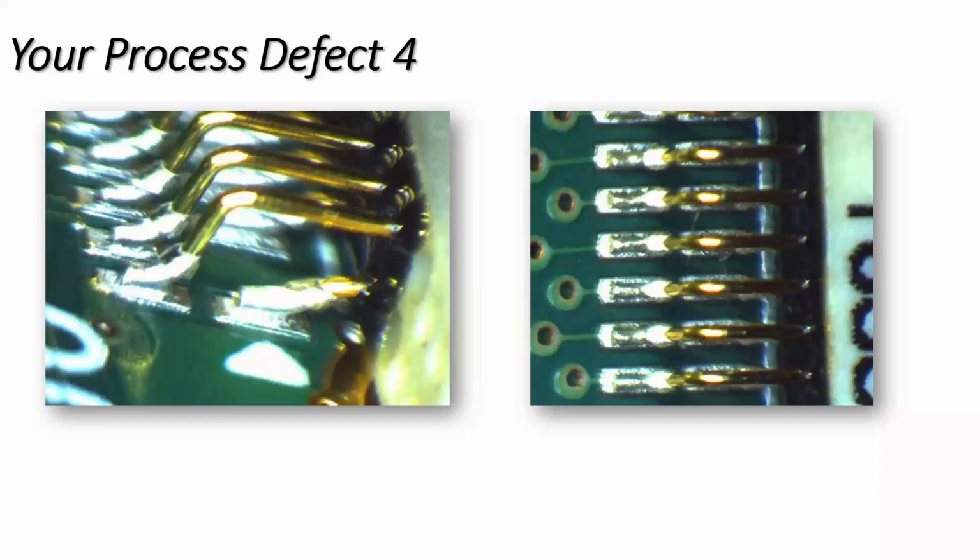So you're actually getting a little bit more energy, and you've got to experiment, because I don't know exactly the oven, the separation distance between heaters, but all you're doing is getting a little bit more energy by radiation into the board assembly. So the solder paste is going to start to reflow based on the board temperature rather than the connector and pin temperature. By doing that, you may well just get enough to reduce the solder paste running away onto the pin.